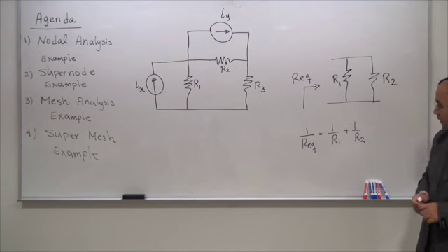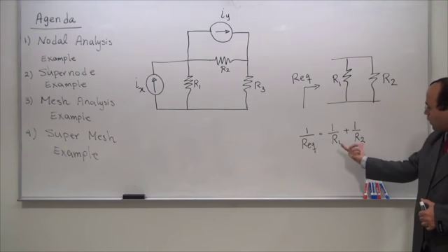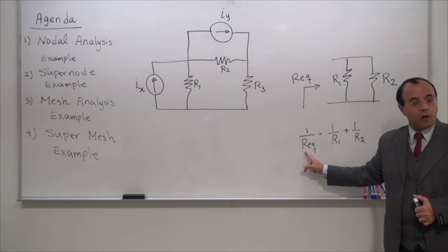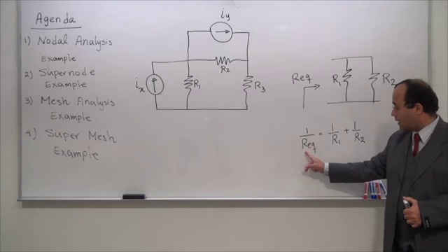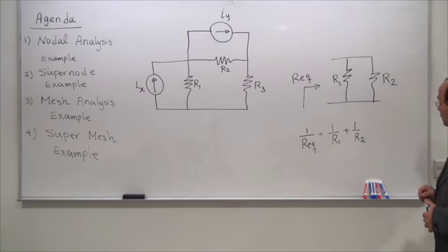So there is a warning here. You have to invert R1, you have to invert R2, you have to sum them up, but when you get to this stage, you have one more inverse to do. So that's why many actually forget about this last inversing action.